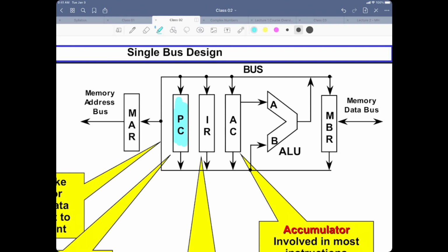Okay, so that's a common mistake, so I'm glad that you said it. Program counter holds an address. Instruction register holds an instruction which has the opcode. So this cannot go into that directly. Go ahead. Memory address register, because I need to read that instruction, right?